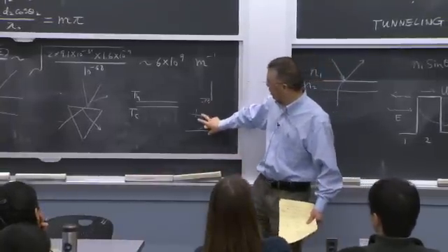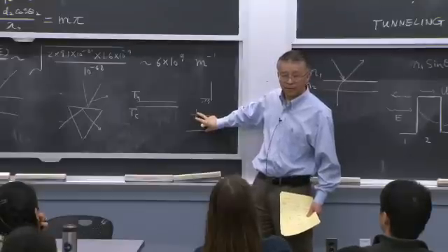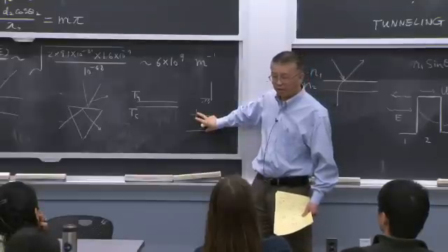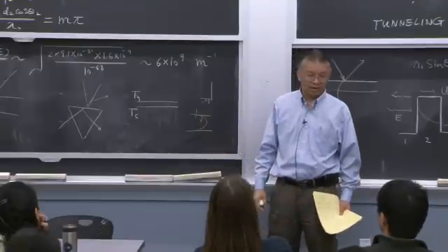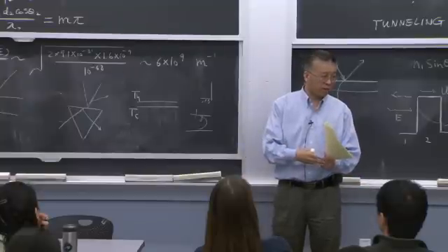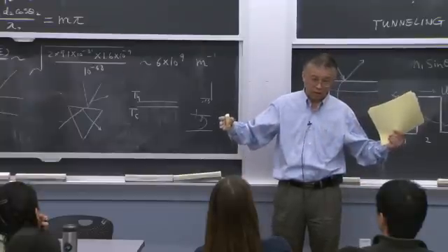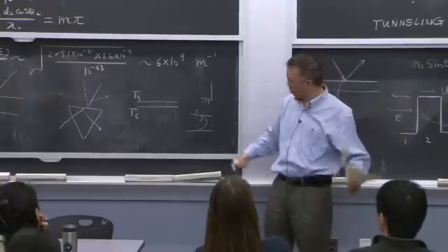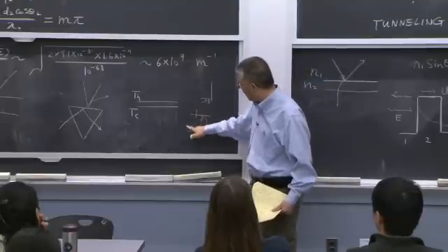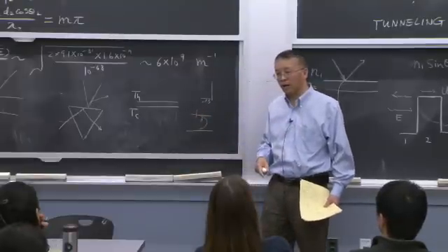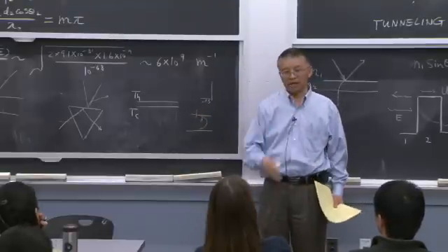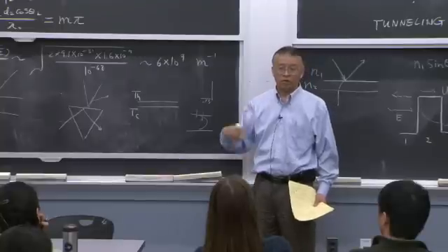Because when you're getting really close, what happens is the tunneling of light actually increases heat transfer, which you don't want in energy conversion, right? So you don't want to get the T hot and T cold too close, below a micron, because radiation tunneling starts to come in and increase your heat transfer.